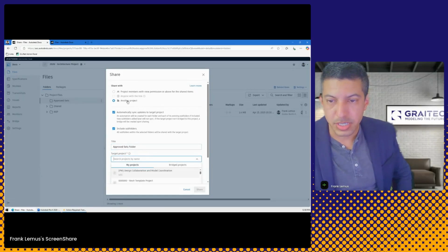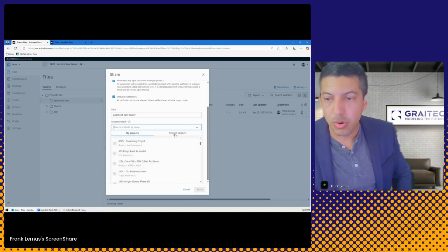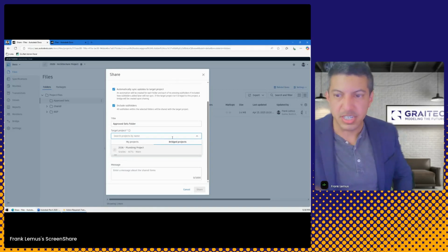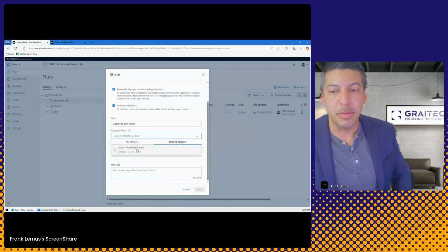To another project, as you can see here. But that can be any other project that I may have connections with, or any other bridge project. I recommend you do it this way because if you do try to send it with a project that you don't have a connection to, you might cause some issues. So just go to the Bridged Projects tab. This tells you which bridges are active in this project, the architecture project. And so I can see the plumbing project is available.